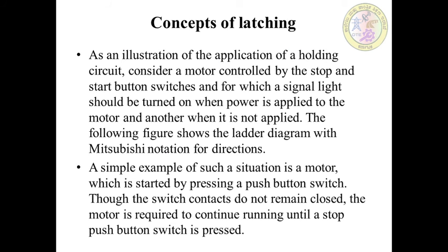An illustration of an application of a holding circuit, considering a motor controlled by stop and start buttons, for which a signal light should be turned on when power is applied to the motor, and another when it is not applied. The following figure shows the ladder diagram in Mitsubishi notation.